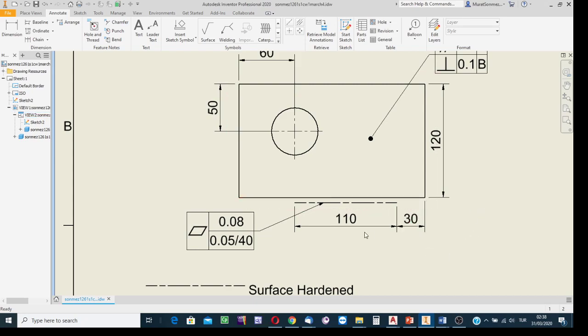This indication, where we have a chain line with the associated dimensions, says that for the portion of the front side surface, it starts 30 millimeters away from the right side surface of the object, and it extends 110 millimeters. There is a special technical requirement to satisfy.